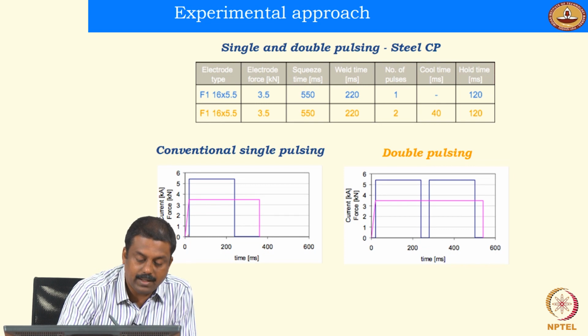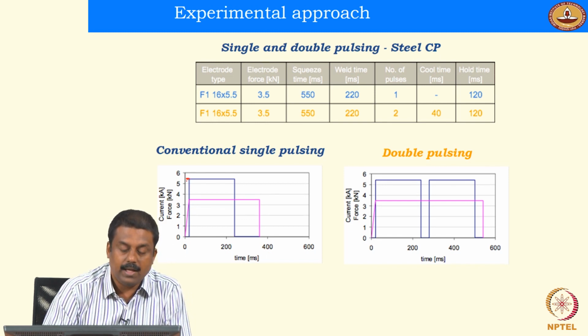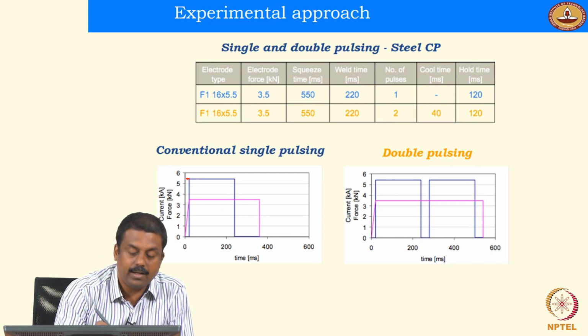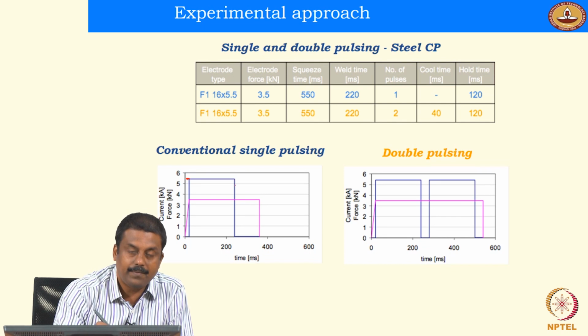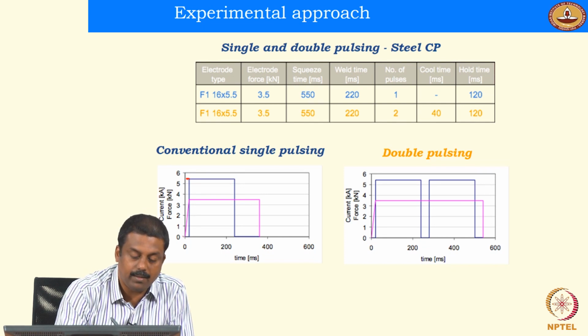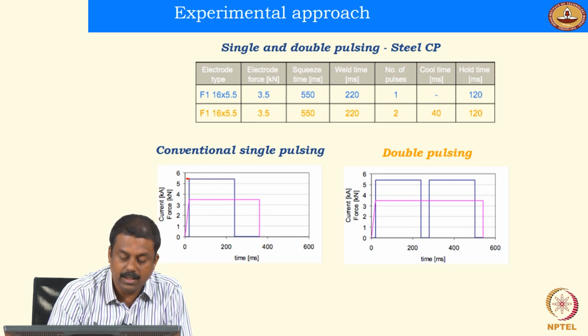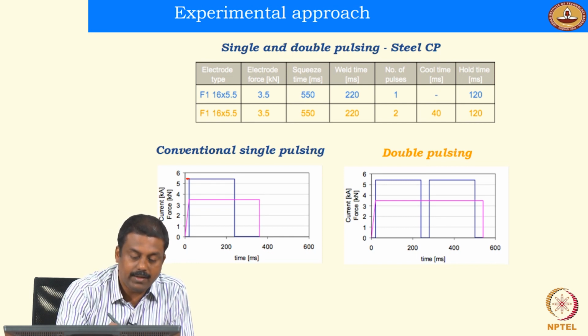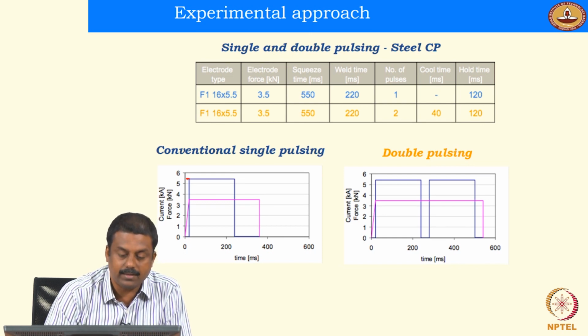We have the current cycle where we give an amperage of over 5.5 to 6 kiloamperes, and we can recall that we can identify the actual current, the amperage, from the weld growth curves. We can apply an amount of load required to keep the faying interfaces together, and then we can play around with the pulsing parameters to achieve varying weld nugget size, right.